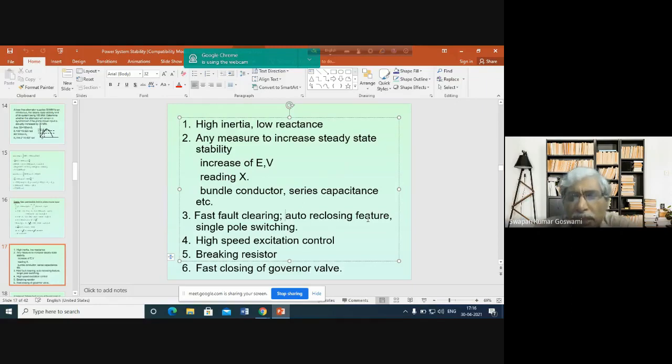Transmission lines are the most probable location for the occurrence of faults, because that is where conductors are used. But of the faults that happen in a power system, at least 80% of these faults are transient in nature. What do we mean by the term transient fault?